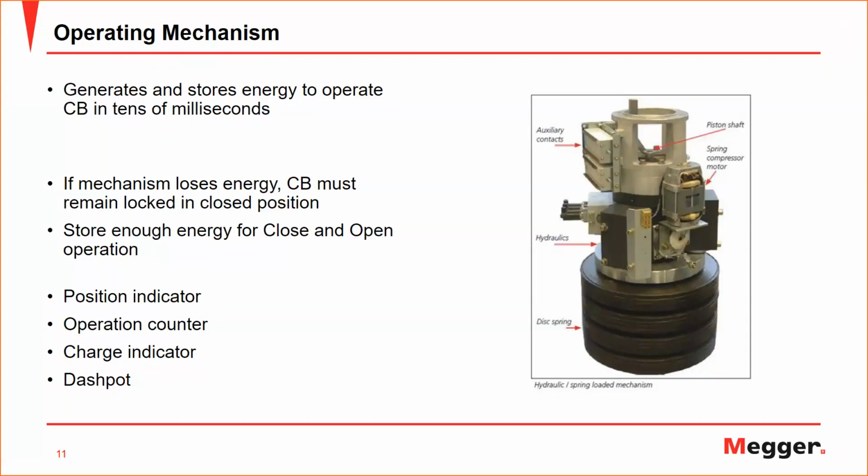And this is very important, because if your operating time is not what it should be or what it is designed to do, and you are opening a circuit breaker on, for example, a short circuit current, there could be a possibility of damage to your interrupters. And not only damage, in some cases, explosions even. The circuit breaker or, for example, the GIS system could explode if the operation is not done correctly.